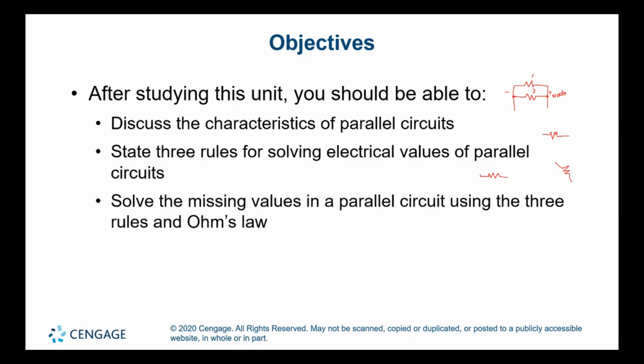I connect 1 point from each resistor with the same wire, and I take my second wire and connect the other point of each individual resistor to the black wire. Now you can see that the 3 resistors share a black wire in common and share a red wire in common. That is a parallel circuit, even when it looks completely different than the one that we have on the top.